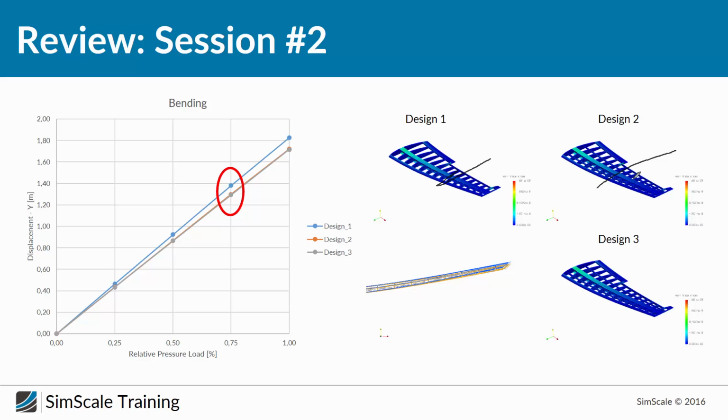What is basically happening is that the stress is now also going through the stringers, and it reduces the overall stress and, for sure, also the displacement of the wingtip. And if we now take a look at the final load stage, let me just clear my sketch.